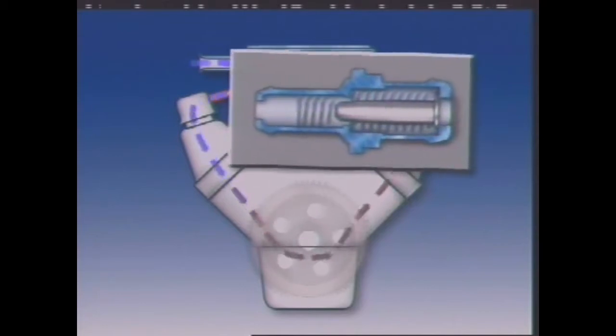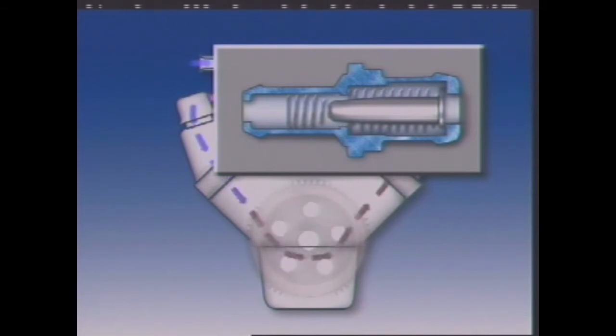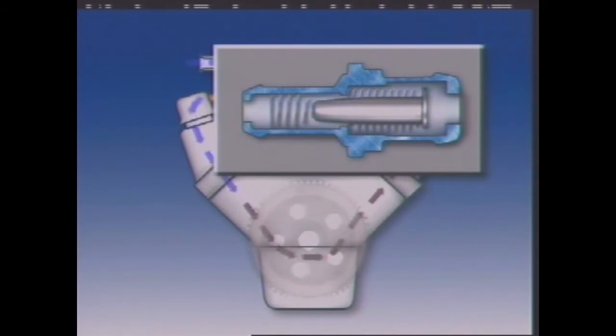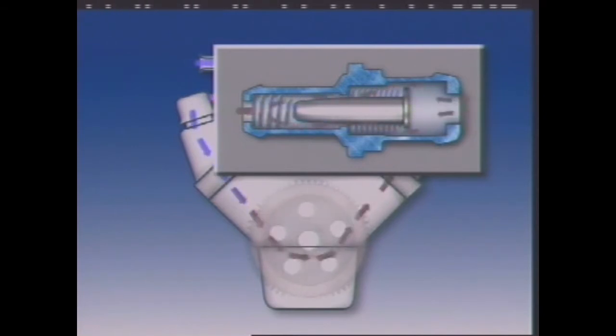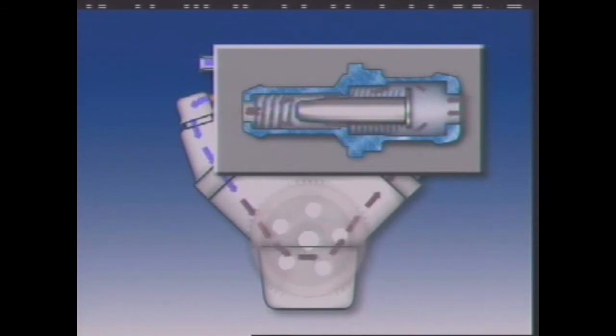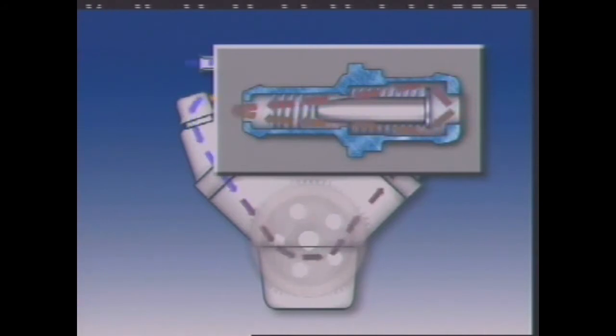It is controlled by the pressure in the manifold. With the engine off, the valve is closed and air cannot enter the inlet manifold. This allows the engine to start. At idle, low pressure in the manifold draws the valve to the other end of the body. This lets a small, measured amount of vapor pass the valve. At wider throttle openings, the valve plunger position allows maximum flow through the body, which gives maximum crankcase ventilation.